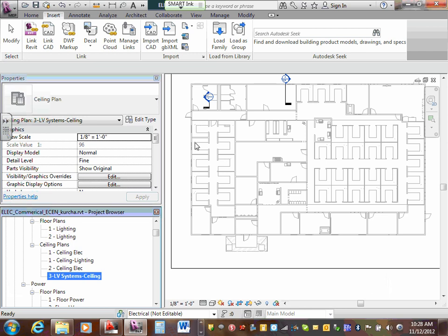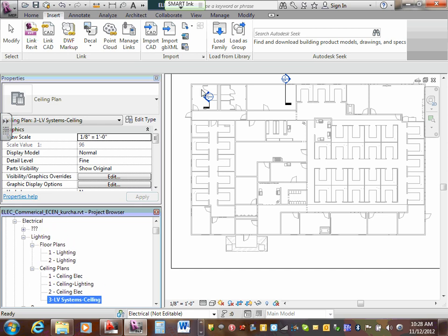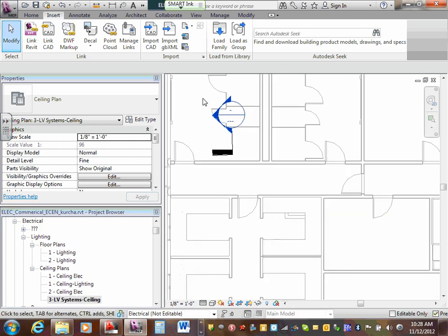Remember the smoke detector criteria for spacing? It covers 30 by 30 feet, 900 square feet. If your room is more than 900 feet, think of another one. Otherwise, how many do you need? One. Let's go to the male bathroom.